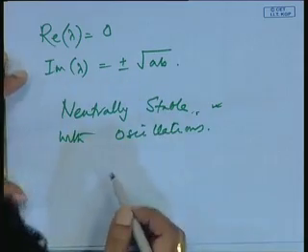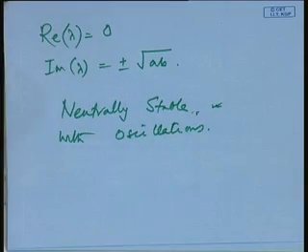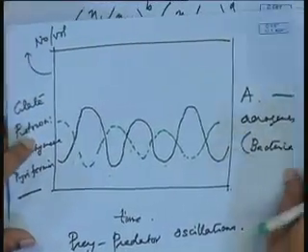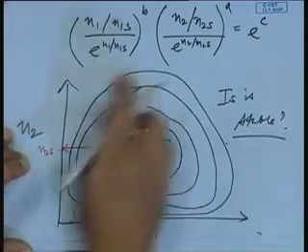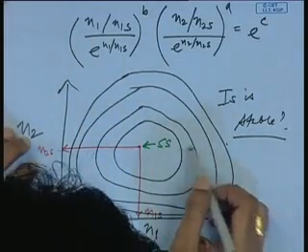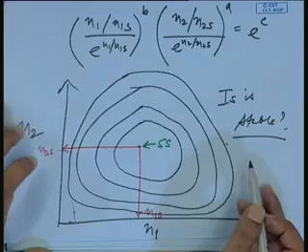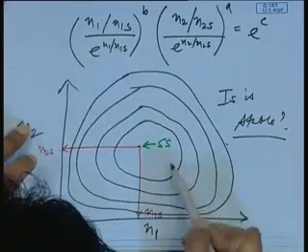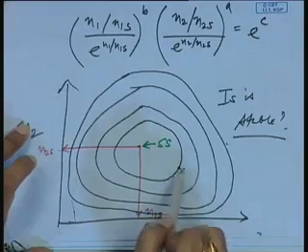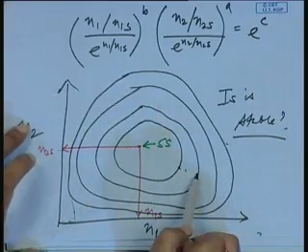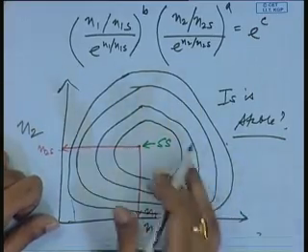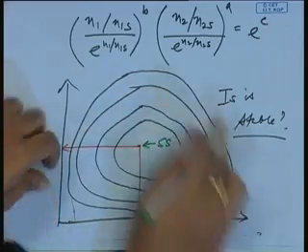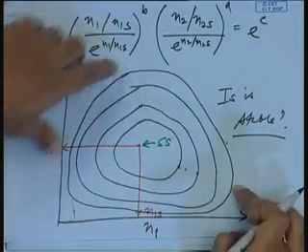So it just remains as it is, and that is why in the pictures that we drew over here, for example this one and this one, these oscillations will continue, and in the phase space also it will keep going on in these circles. Now you can ask me, what are these different circles about? Why do you have so many different circles? It depends on the initial condition. Remember, these are dynamic equations we are solving. For one set of initial conditions we will be on this trajectory, for another set we could be somewhere here, and if you keep changing the initial condition, you could go further away from the steady state. But remember, these are dynamic systems, so they all depend on the initial condition.